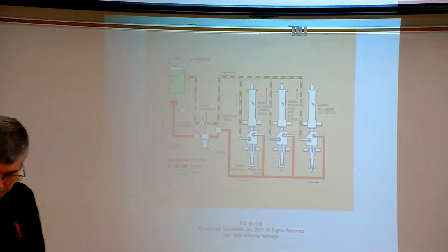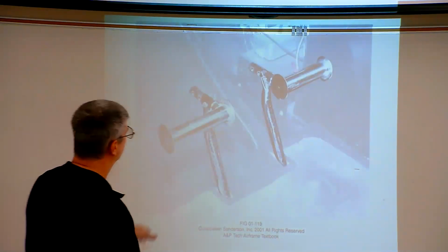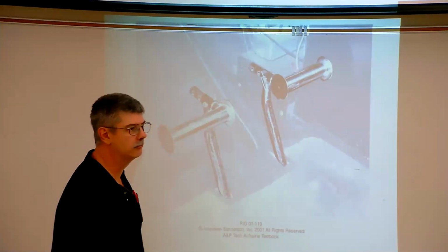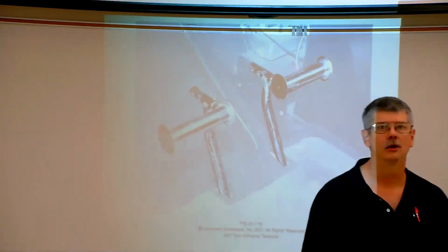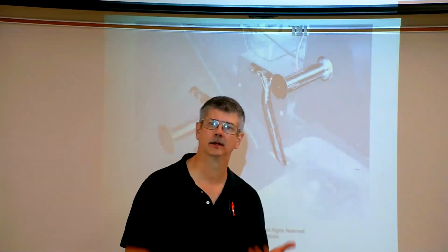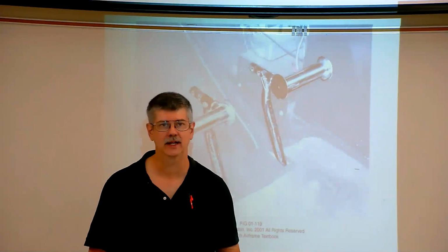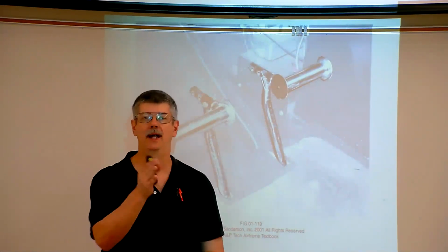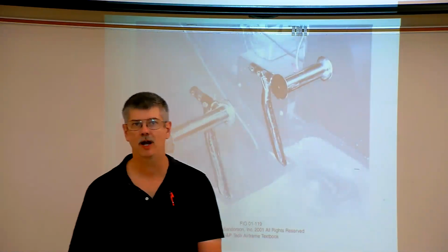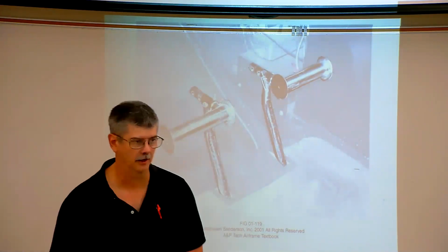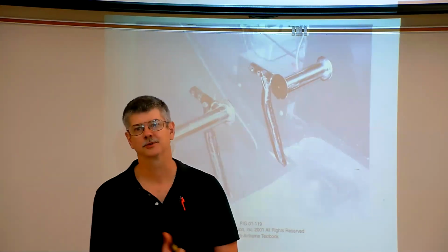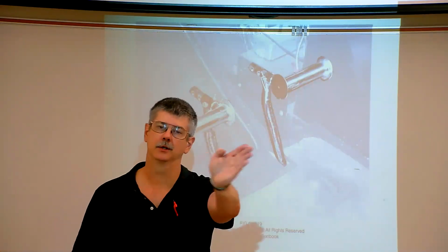Torque compensation, I kind of already talked about it, you know, through the anti-torque pedals. Many people call them the rudder pedals. If you push on the right anti-torque pedal, what it actually does is it decreases the tail rotor's angle of attack, which produces less thrust or lift. And by doing that, the torque of the main engine or the rotor blades makes the nose go to the right. When you push on the left pedal, you increase the pitch of the anti-torque rotor, which pushes the tail to the right, making the nose go to the left.